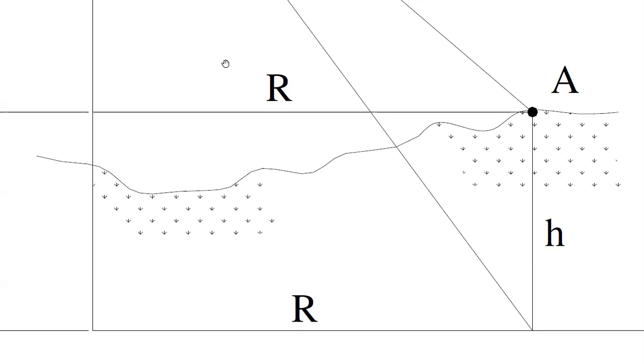It is literally the representation of these forms, or something that has a height on a photograph, it creates an error. Okay, it creates an error, and we want to look at what it is. We can also call it displacement, because in this particular lecture, we want to bring your attention to the ability to calculate the height of an object. Are you okay? Using this equation. All right. So the relief of point A, or the height of point A, is actually h subscript A. Okay. And it's usually above datum.